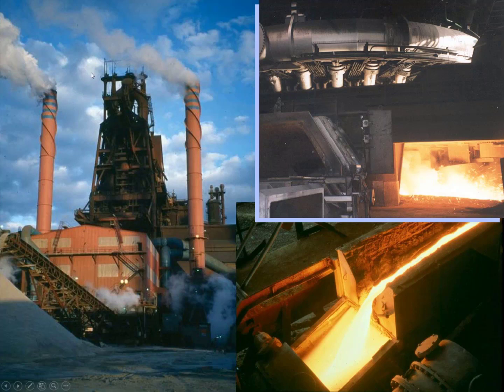So again, there's a picture of a blast furnace on the left, and there's a couple of stacks which are from the granulator units, which are down below. And on the upper right, you see the blast furnace, and they're tapping off the slag out of the furnace there into a runner, and it comes down the runner, and then it's fed in the lower right into a stream of water, and that's where it gets granulated. It goes from 1500 degrees down to almost room temperature in a few seconds.